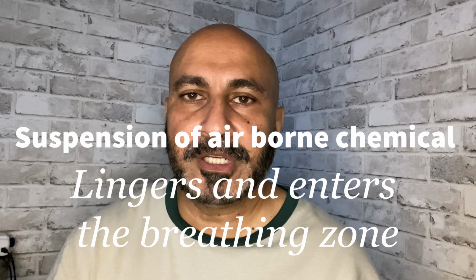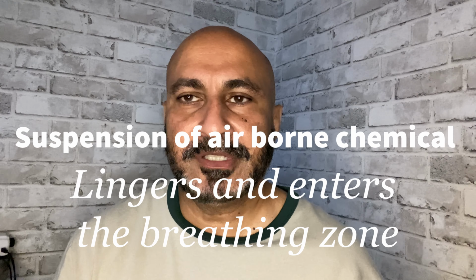So that ability, that suspension, is going to be an issue, because when that suspension takes place, that's a hazard, right? So what's going to be the risk? A person lingering, an occupant being in that room, is going to get that suspension of the airborne contaminant into the respiratory system. And that will get introduced into your breathing zone. Breathing zone is basically something from the nostril. I mean, breathing zone is an imaginary sphere around your face. Let's say from your nostril, you take 2 feet. Try to create an imaginary space.